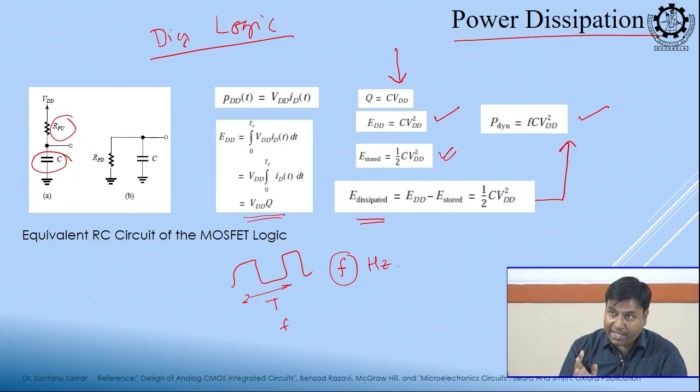The rate at which it is switching matters. If it is switching very fast, it will be dissipating more. If it is switching very slow, it will dissipate less, right. Higher frequency, you can check your processor or your mobile phone. Higher frequency means higher power, right, nothing comes for free. If you try to run at higher frequency, you will also have to burn higher power, because it is switching more often, right.